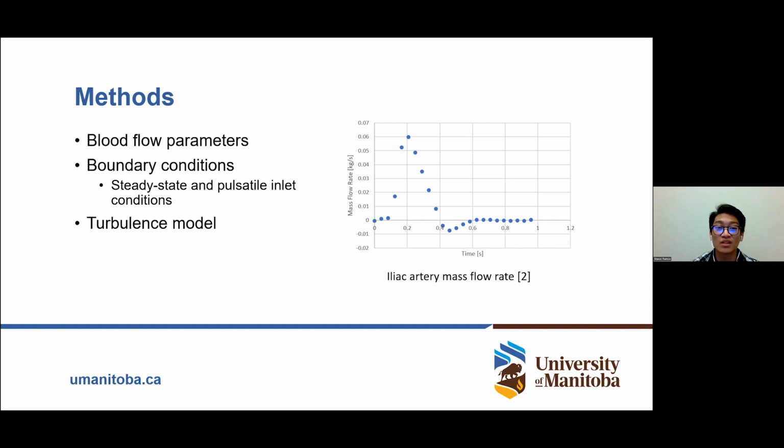A turbulence model was applied as diseased arteries have been observed to cause turbulent flows. As the endograft limb geometries more closely depict diseased arteries, a turbulent flow was assumed in this study. A K-epsilon model was used for the rate at which convergence can be achieved and the relatively low computational requirements relative to other models.